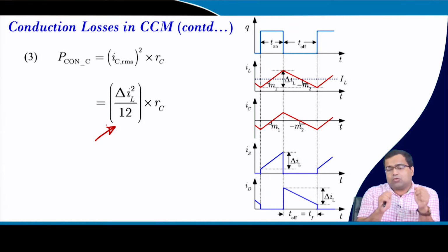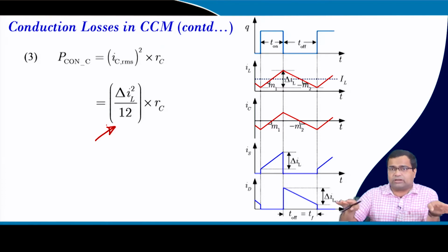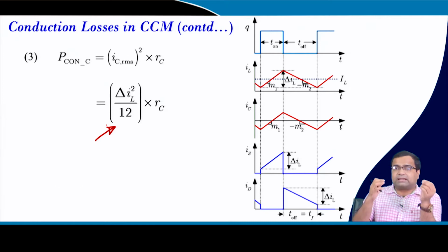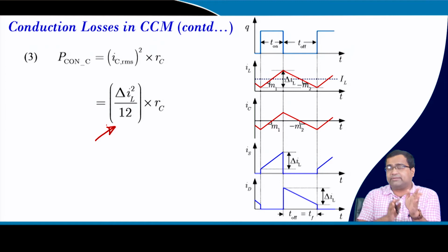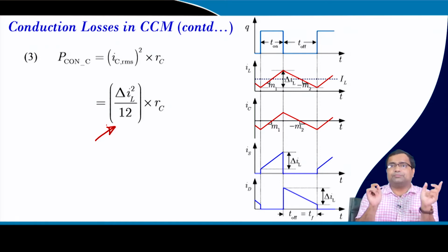Now, when you are talking about a very light load condition, there are scenarios, if you talk about LED driving, dimmable LED, particularly PWM dimming, where the LED string will be connected and disconnected. Suppose a buck converter is driving an LED; once it is disconnected, the output current of the buck converter is 0.